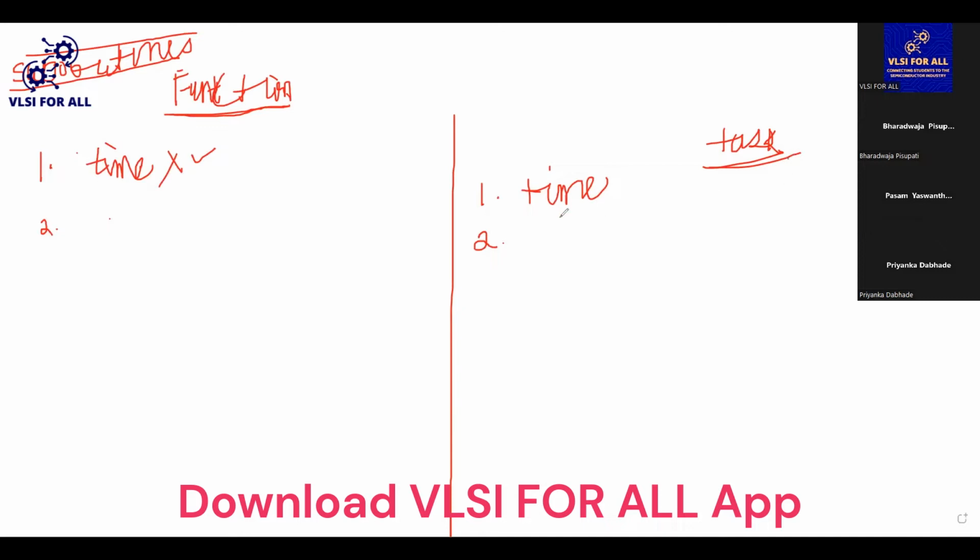But inside a task we can use timing, and if we use any timing inside the task, it is not synthesizable. Functions are simulated in zero time, and in tasks, if we give any delay, it will run according to that delay or according to the passage of the clocks.